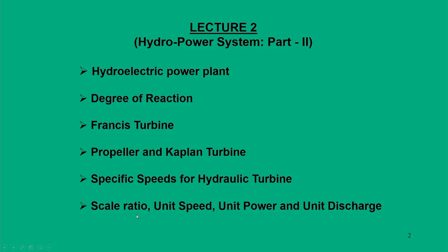To do that, we need to maintain the model size and designs, and for that reason we are going to define certain parameters like scale ratio, unit speed, unit power and unit discharge. So, this is the overall philosophy for our lecture.